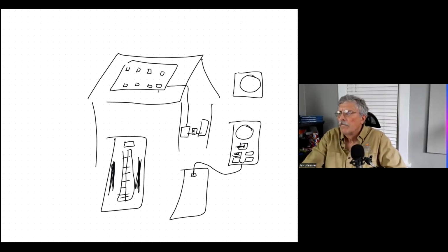All right, so the neutral, the white wire, and the grounding wires are bonded together in this main breaker. But because there is a jumper or some sort of bond between them, you could intersperse your white wires and your bare copper wires in these bus bars. And oftentimes, and you should look in your circuit breaker panel and see if they're all mixed together, because that's pretty common. That can only happen in the main disconnect box.